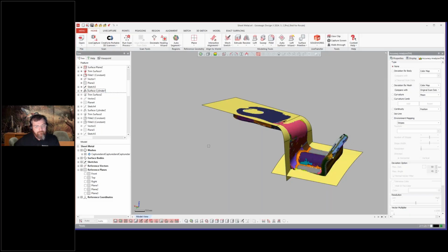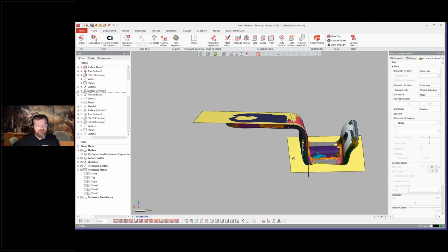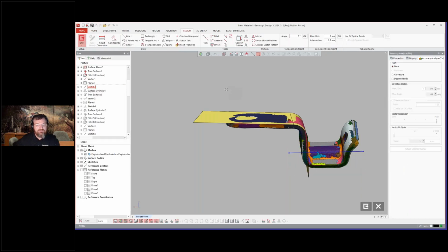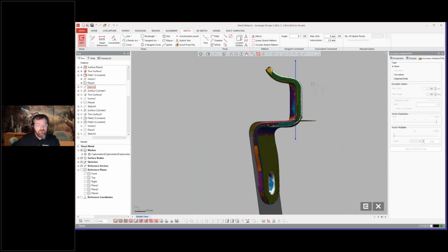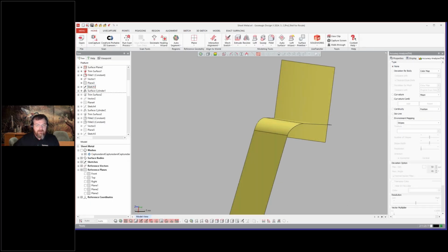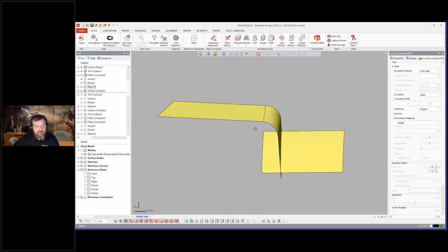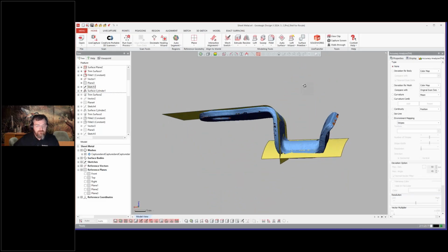We're on the bottom. You'll notice that those regions, as I rolled over before, are considered a cylindrical region. So we went ahead and modeled that, and you can use the extrusion wizard to do that, and it will create an extruded surface, and it gives you the history, so you can come over to the sketch as well, and then you can go normal to, and you can redraw that. If I turn my mesh off, I'm just going to hit delete here. So whatever way they did that, they must not have used a mesh sketch to do it.